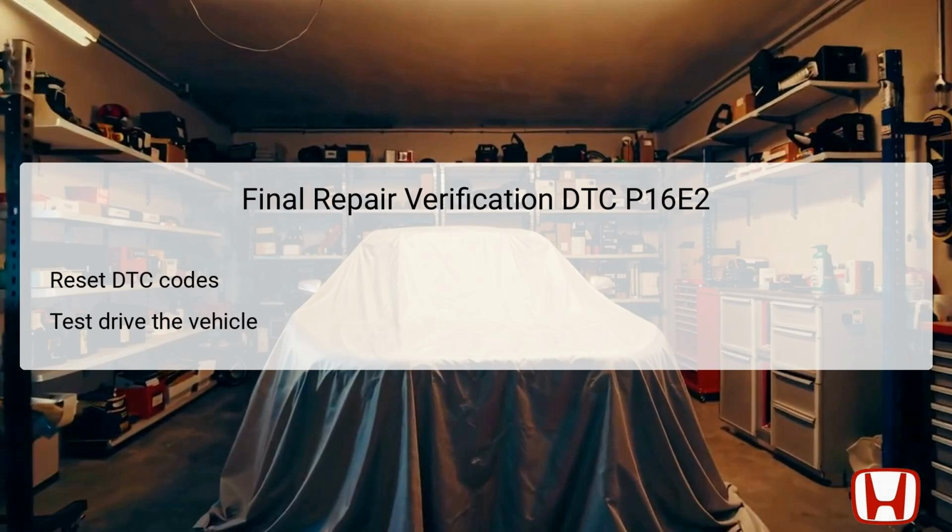Once all necessary repairs and inspections have been completed, the final step is to perform a reset of the DTC codes. This process allows the vehicle's PCM to clear any stored faults relating to DTC P16E2 and prepare the vehicle for a normal state of operation. Following the reset, a test drive should be conducted to assess the overall functionality of the vehicle.